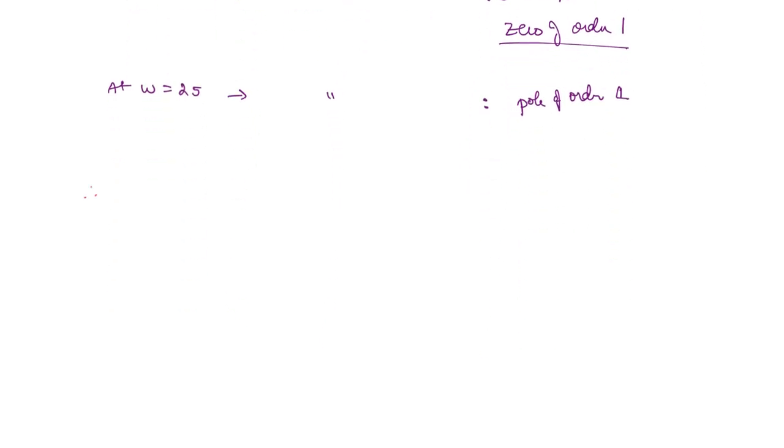So therefore, you can finally get the final transfer function. You have the constant as 100 and there is going to be a 0 at omega is equal to 5. So what will it be? 1 plus j omega by 5 divided by how many poles are there at origin? The order of poles at origin was 2.